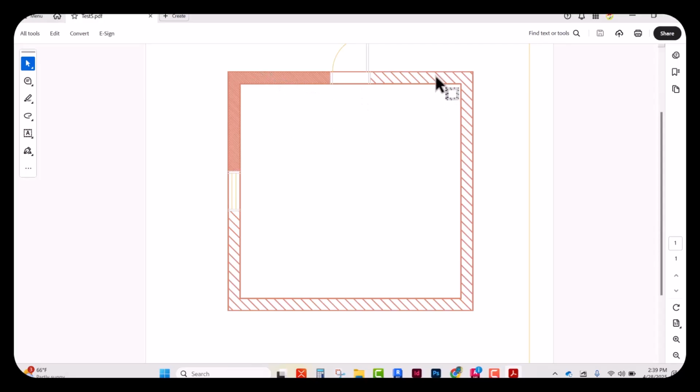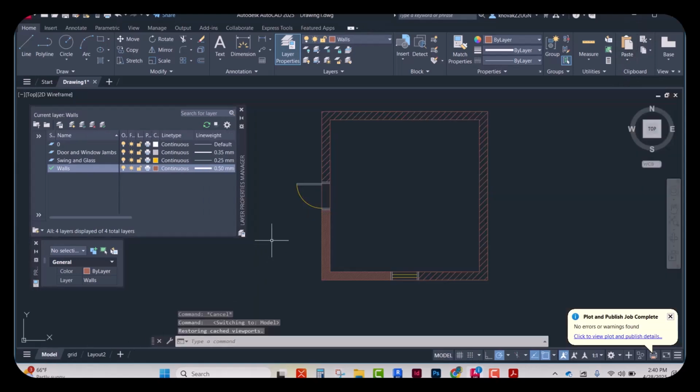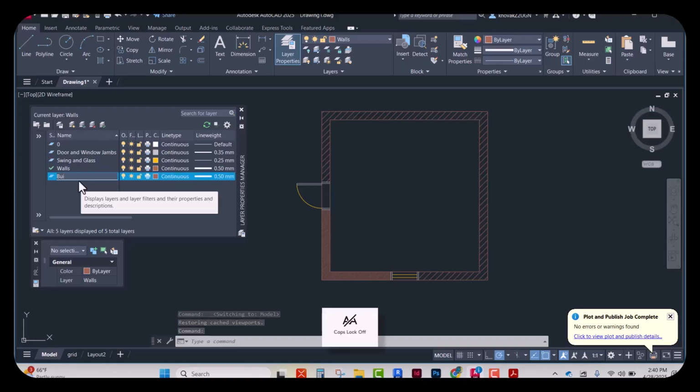And depending on your needs and what your aesthetic choices are, you can do all sorts of different poches for your wall. You'll also choose a different poche for casework. So something more open like this would be for casework. Talking more about components, furniture versus built-in, like casework, those would also be different line weights. They wouldn't be drastically different, but you would want to show a difference. And so you would create your new layer, name it, and then choose your color and choose your line weight.